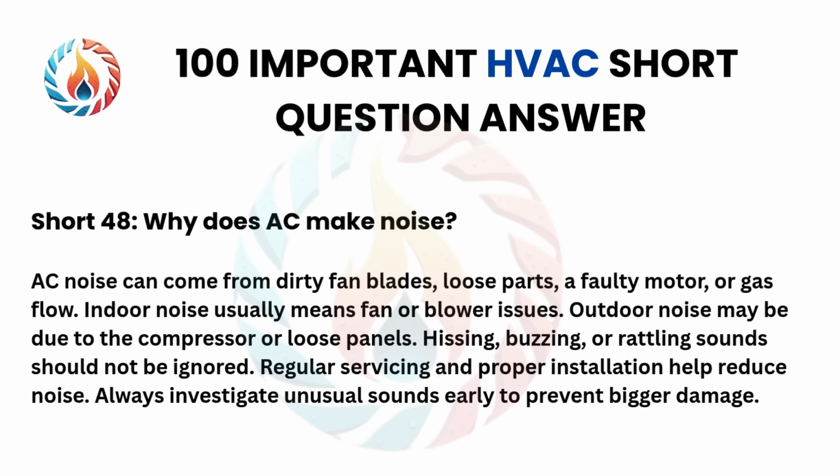Short 48. Why does AC make noise? AC noise can come from dirty fan blades, loose parts, a faulty motor, or gas flow. Indoor noise usually means fan or blower issues. Outdoor noise may be due to the compressor or loose panels. Hissing, buzzing, or rattling sounds should not be ignored. Regular servicing and proper installation help reduce noise. Always investigate unusual sounds early to prevent bigger damage.